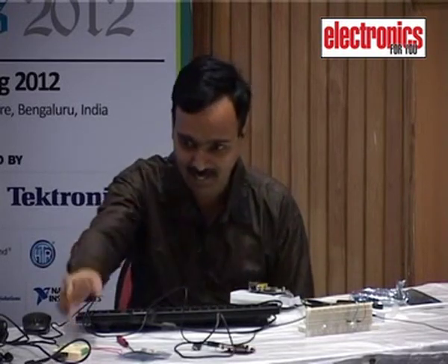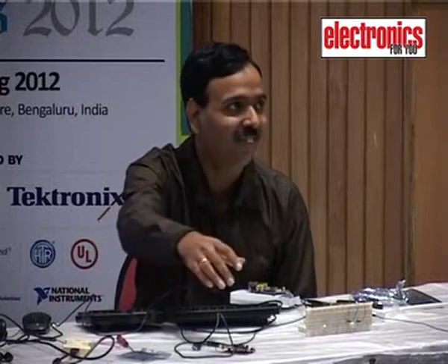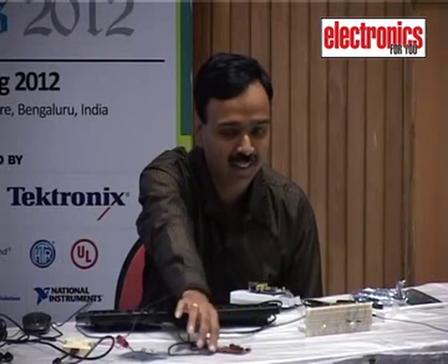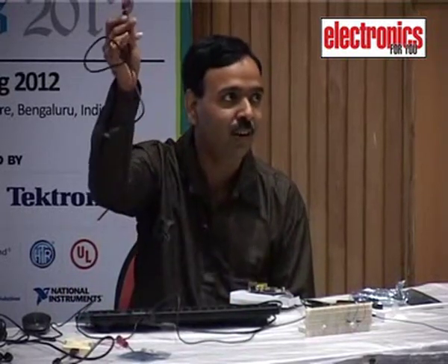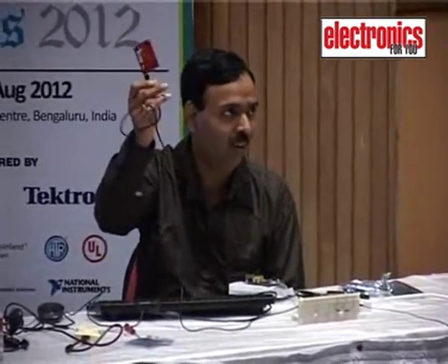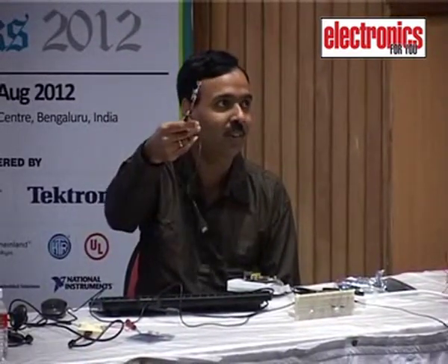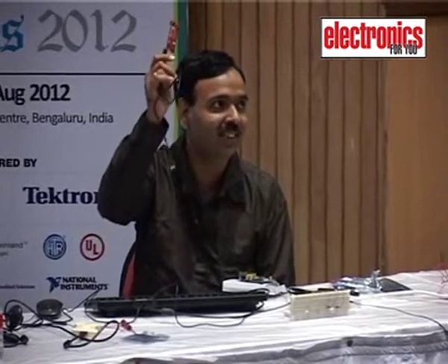Then in that case, possibly we could scale down the number of tasks or threads that the OS is running, so that our response becomes closer to real time. But all those things are fairly involved. What I'm doing is, the easier solution is to have an Arduino or something like a MSP430 Launchpad, a simple microcontroller, interface with the USB port, and do your real-time stuff using these things.